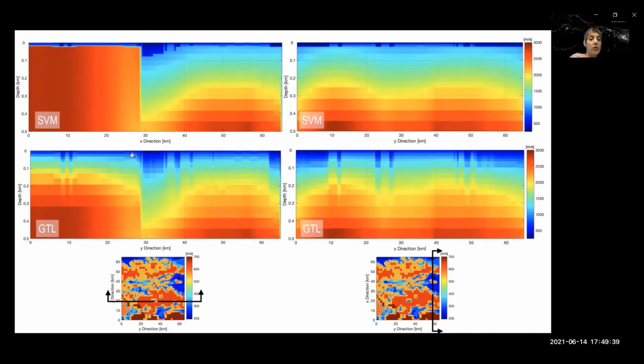GTL, on the other hand, so long as there is a VS30, the profile has to match at 350 meters per second, 350 meters depth, and you can see this alters this basin edge. Similarly here, we have some discontinuities, mostly coming from the fact that some VS30s are actually measured, whereas others are inferred.